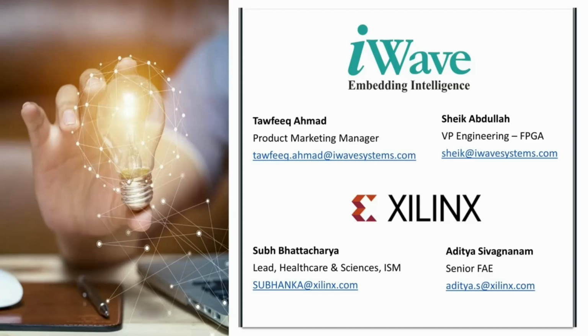Sheikh, one more question for you. On one of the slides you mentioned 100G Ethernet as a feature of the SOM. Do we have any solution for 100G Ethernet? Yes, we already validated Xilinx 100G Ethernet along with ERNIC in one of our development kits. ERNIC is nothing but an embedded RDMA enabled NIC IP used to achieve maximum throughput using 100G Ethernet. So we do have that 100G solution using our SOM based development kit.